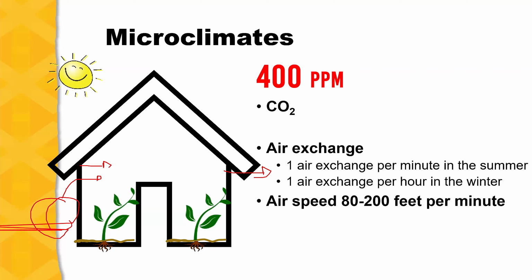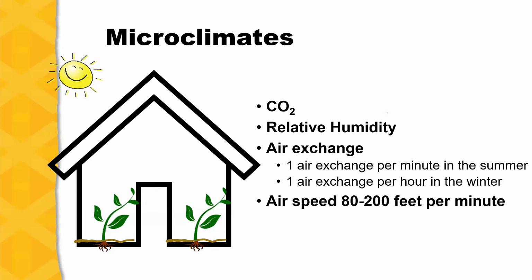But there's another reason why you want to have air exchange in the greenhouse, not just because of the CO2, and it's relative humidity. Remember what I mentioned earlier when we talked about water uptake for plants? When the sun heats up the plant, it creates a lot of vapor pressure, right? If you have, during the winter, this structure closed, because you want to conserve heat energy, you don't want to spend fuel heating up the greenhouse, you want to conserve that heat energy.